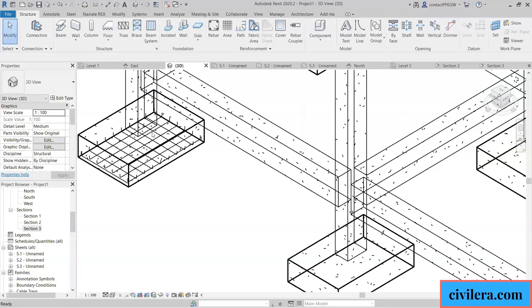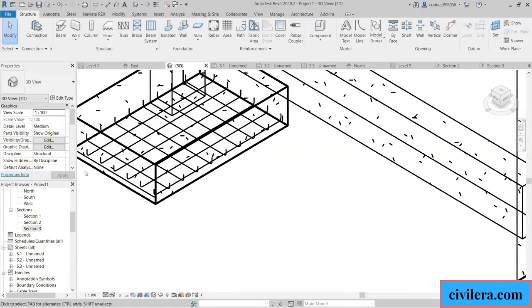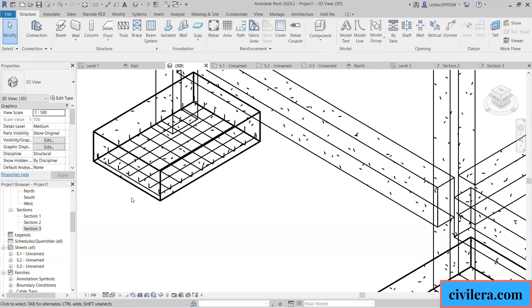If you want to see that in 3D, you can see that both direction rebars are placed. Which layer is first, which layer is second, you can decide all that based on your design, short span first or long span first. Generally, the footing cantilevers will be the same, so your moments in both directions should be the same as long as you are able to achieve that. So whichever is the first layer doesn't matter. But still, if you have any preference, you can do that as well. So that's how you do rebar detailing. It's very easy to produce design intent drawings, but if you want to create bar bending schedules, it's a little difficult in Revit for difficult beams.